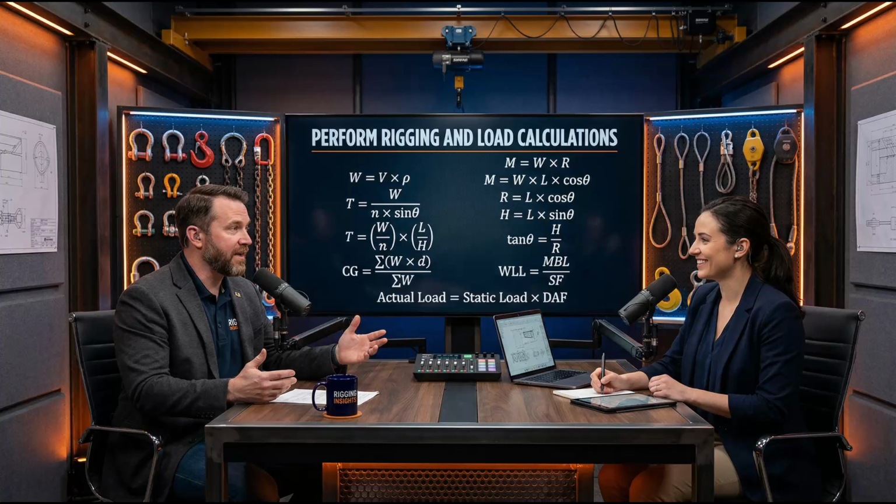Okay, so using the field formula, you take the length of 29.7 and divide it by the height of 25. That gives you a multiplier of roughly 1.18. You then take your 50-ton load, divide it by the number of slings to get the base weight per sling, and multiply by that 1.18 factor. Within seconds, standing in the mud, you have mathematically proven the exact physical strain your rigging is about to endure. And you can verify if your equipment is rated to survive it.